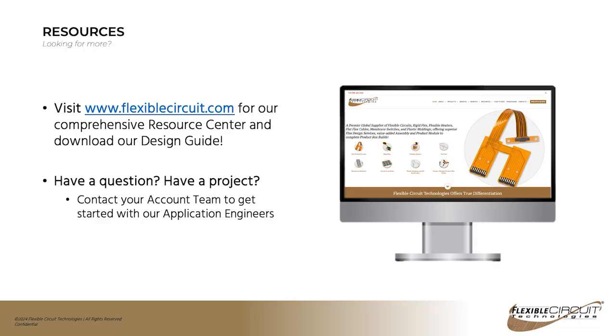What is the smallest bend radius that the flex can bend to? Mark? Yeah, that's a very good question. The smallest bend radius is typically driven by the circuit type and the circuit thickness. The thicker the circuit is, the greater that bend radius has to be.